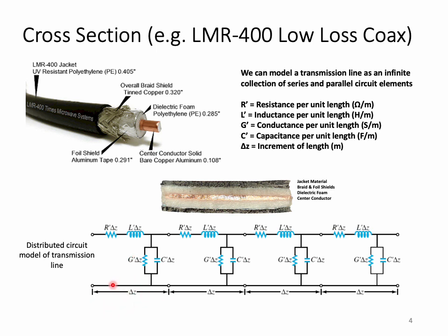Heaviside took these small infinitesimal models and then strung them together to form the cable and looked at what happened when delta Z goes to zero. So as delta Z goes to zero, we get a better and better approximation to the characteristics of the cable. This approximation technique is probably familiar to those who have taken a course or two in calculus.